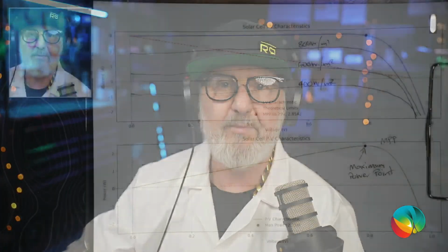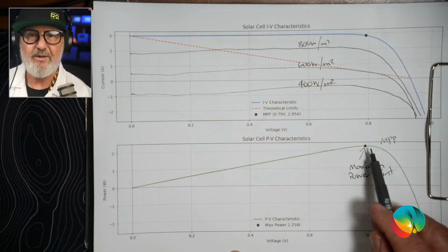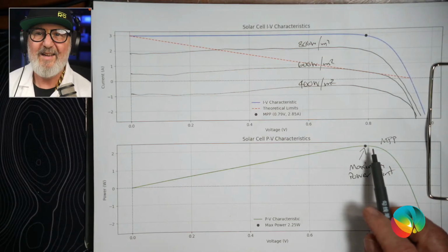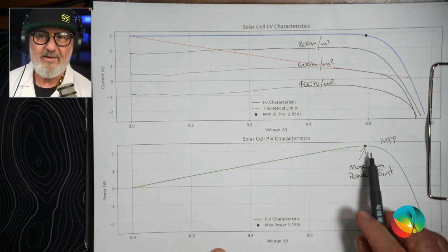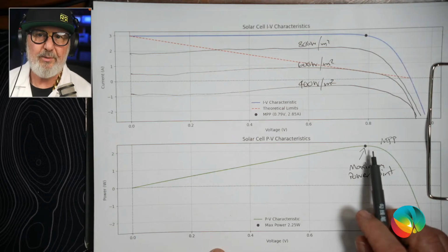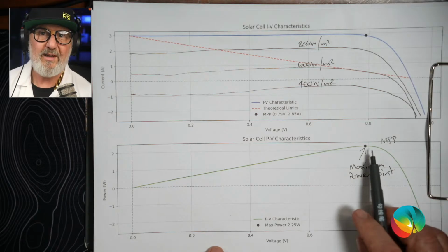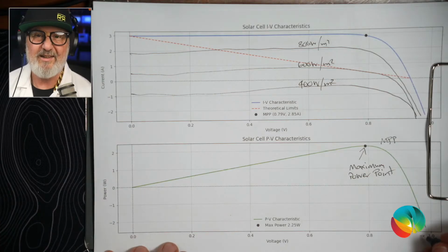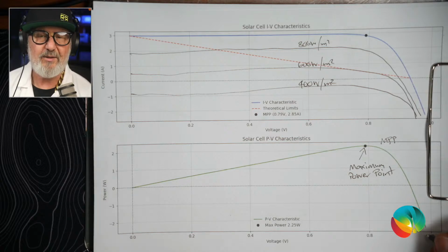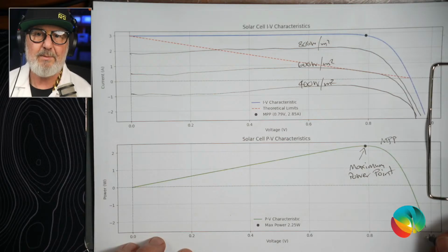So let's go back to my little diagram here. I said that the maximum power point was here, but then I went on to say that actually it moves around with irradiance and with temperature. So how do you find it? Well, it's a little algorithm called perturb and observe. Perturb means change stuff, and observe to see what the outcome is. So when an array first sees sunlight, its voltage goes up to open circuit because it's not drawing any current yet. The charge controller or the MPPT can determine when it starts to draw current. So it's effectively a smart load.